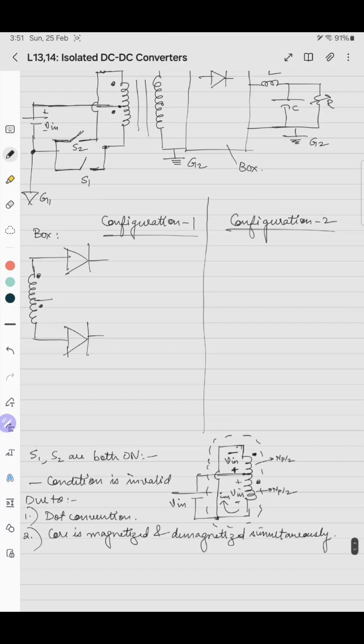So on the secondary side, what we can have is two diodes, then we need to have the inductor like this and the R. Then how to connect it? So it's a secondary center tap. So let's say this is plus minus, this is plus minus. What happens is the common terminal here should be taken as the ground, as a new ground.